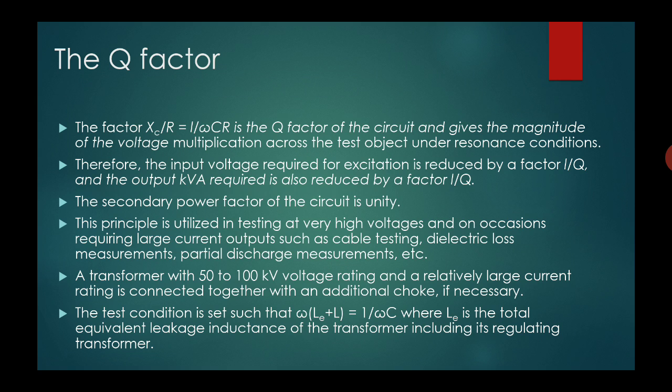The test condition is set such that omega (Le plus L) equals 1 by omega C. That is, Le is the total equivalent leakage inductance of the transformer, including the regulating transformer.